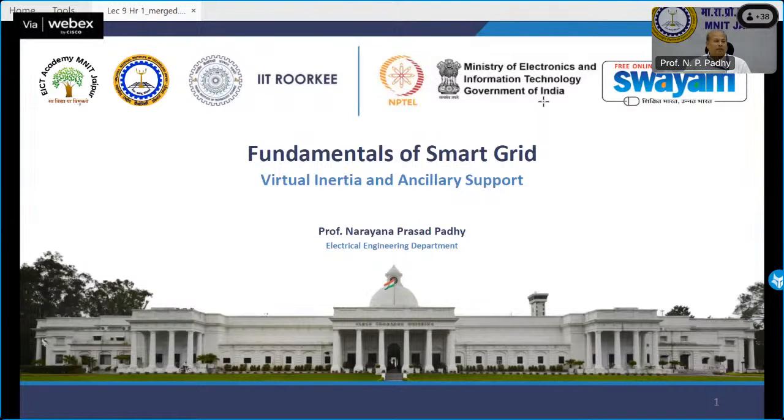Because previously it was government owned, and I do have a synchronous machine in which you have a PQ characteristic, and it is like a circle. You can have maximum Q and 0 P, or I can have maximum P and 0 Q. That is P squared plus Q squared equals S squared, which is a circle equation. But when I say money will be paid only for P generation, then I'll try to make my volt-ampere equal to watt, so that I get maximum money out of it.